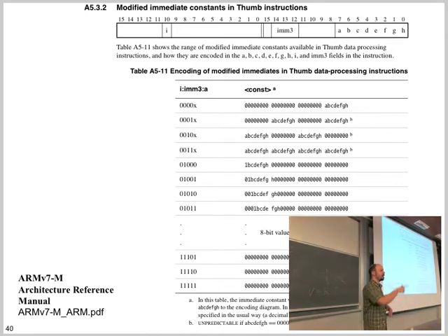Yes? So is what that's saying is it's using the I, the 10th bit, the immediate from the 14th down to the 11th bit, and then the A from the 7th bit? Yes. To do that encoding? So one little note here. As you can see, it's actually partitioned into 0 to 15, again 0 to 15. So that's 0 to 32. It's 2 half words. So in total, it's one 32-bit word that gets read. It's just how they write it into 2 different parts, because sometimes you can have 16-bit, sometimes 32-bit operators.